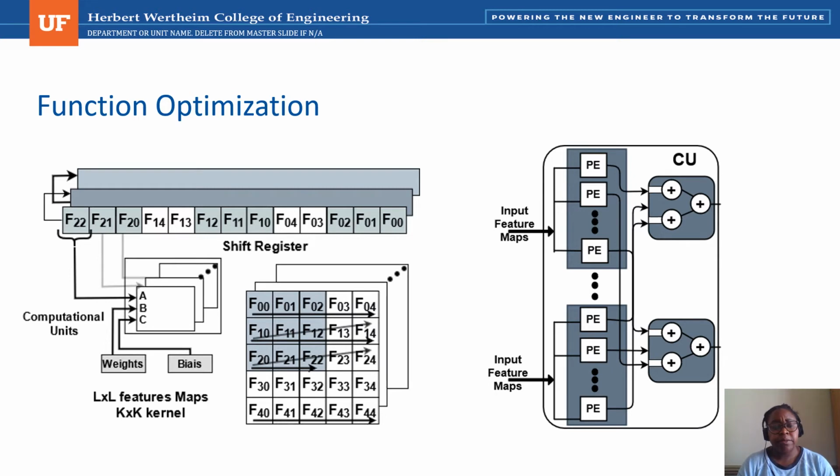In this slide, we present a basic architecture of a convolution layer. So we assume that this is the input convolution that we receive. We have a 2D feature map with a certain number of channels. The input feature maps are processed according to the arrows presented in the picture. So the inputs are first loaded into shift registers, which are considered to be on-chip memory, on-chip buffers, and we have several on-chip buffers.